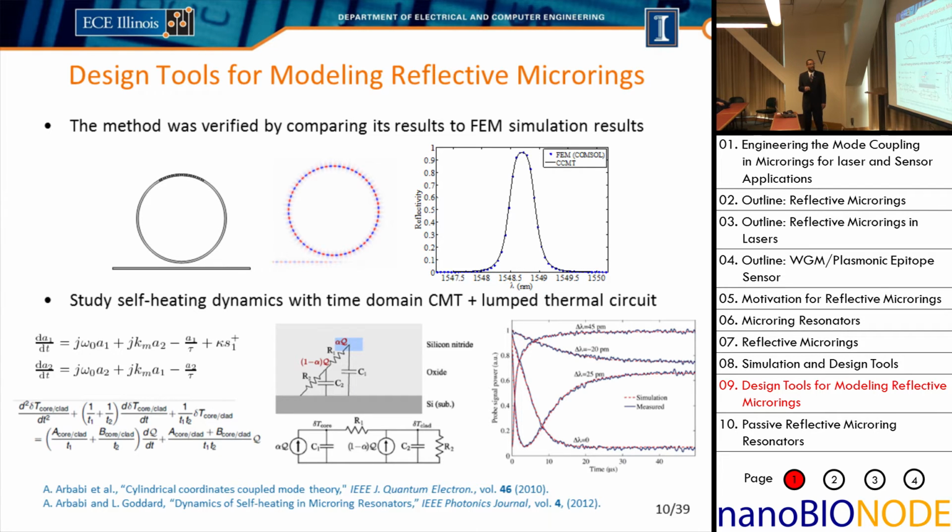And then there's thermal resistance between the core and the cladding, and between the cladding and the substrate. And these are also heat storage materials. So there's a thermal capacitance from the core to the substrate and from the cladding to the substrate. And we get an equivalent circuit model that looks like this. So there are heat sources and there are capacitances and resistances in the structure, and you can calculate the temperature at different parts of the device.